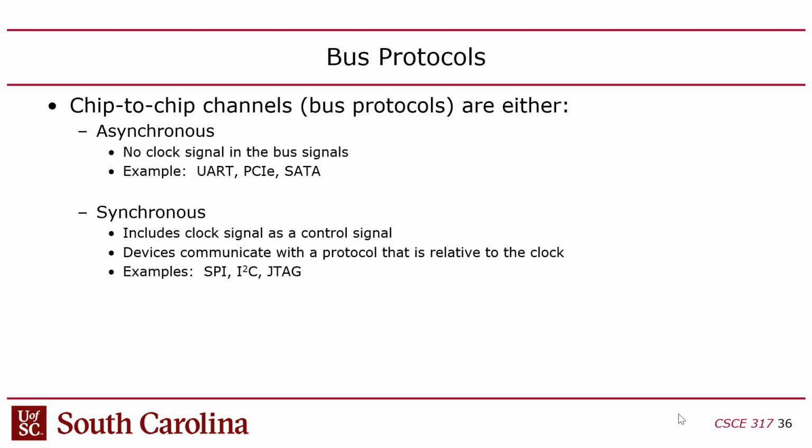So some protocols are asynchronous. We talked about UART, which was asynchronous, and the way it was able to get around having a clock was that both ends just had to agree on a baud rate, right? Which is a constant issue with UART. If any of you have ever used UART, you almost never know what that's supposed to be, and it ends up being a trial and error thing.